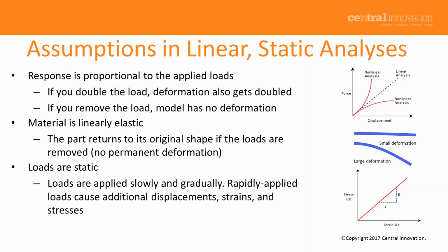So that's called nonlinear. Most of the, let's say, ductile materials, such as steel product, have a very significant linear region. And this linear region will remain until the actual material comes to a point where it is not acting linearly anymore, and that's what we call yield.